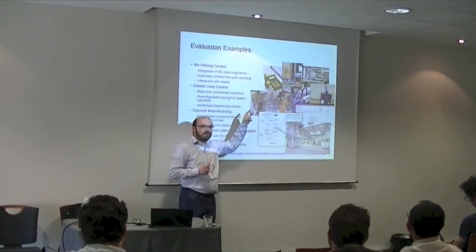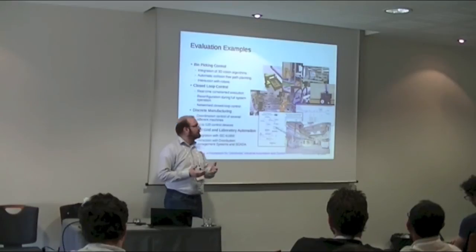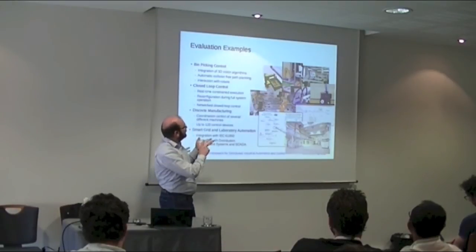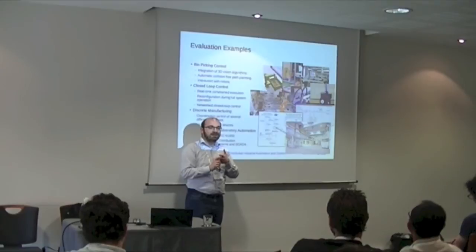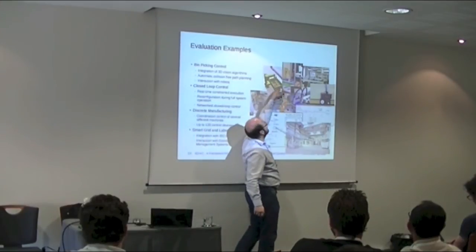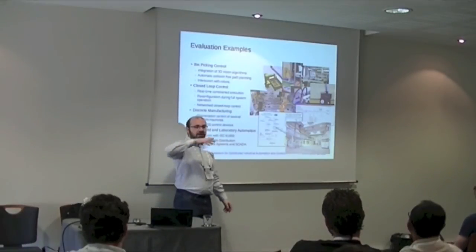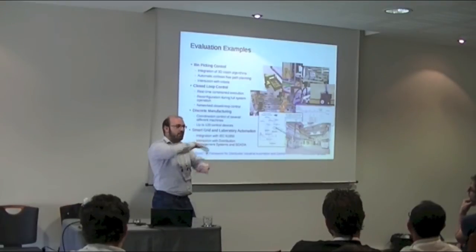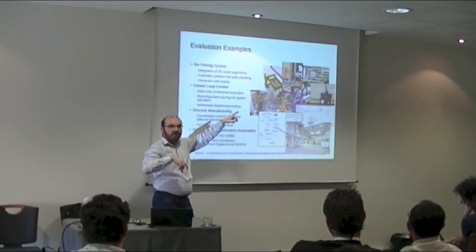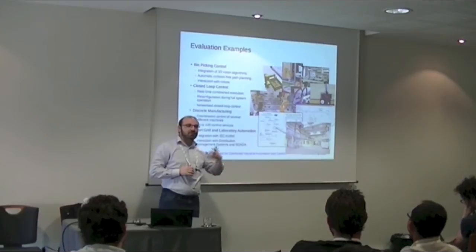And these applications are very interesting. There, 4DIAC is used not as real-time control environment, therefore it's used as sequencing and coordination environment. There we have 3D scanners, cameras, industrial robots, grippers, humans, mobile platforms, and these are coordinated. So this is a bin picking application where a 3D scanner checks how the parts are lying in the bin, another system is then taking the 3D information from the 3D cloud, calculating which parts are lying on top of each other, which one can be grasped next. And from this information a path is calculated for the robot, and the robot then can pick it and put it on a conveyor belt and so on.